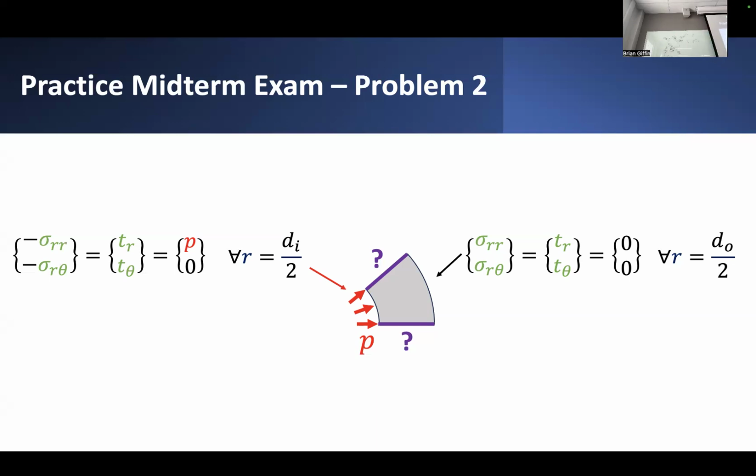Same thing if, across the symmetry plane, points wanted to pull away from this interface. If we're assuming it has to be symmetric, then it would imply there's some kind of fracture opening in this thing. So to satisfy compatibility across the symmetry plane, what we require is that the displacement normal to the symmetry plane has to be constrained.